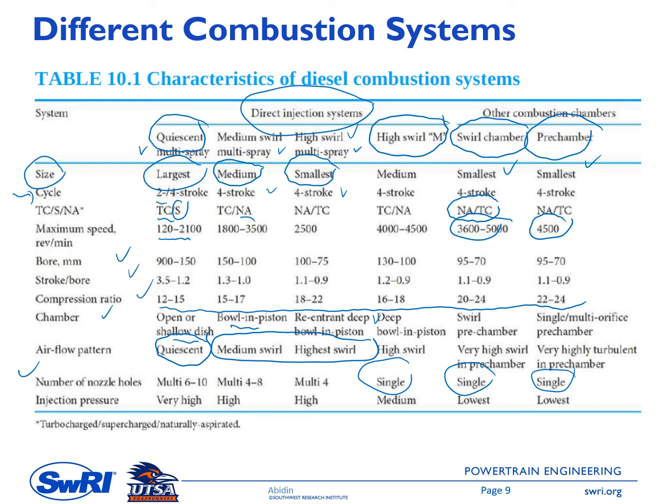And then the last category you can see in here is the injection pressure. For the large engine, usually it has a very high injection pressure. The reason for this is because you need to inject more fuel, and usually it has a slightly higher nozzle diameter.